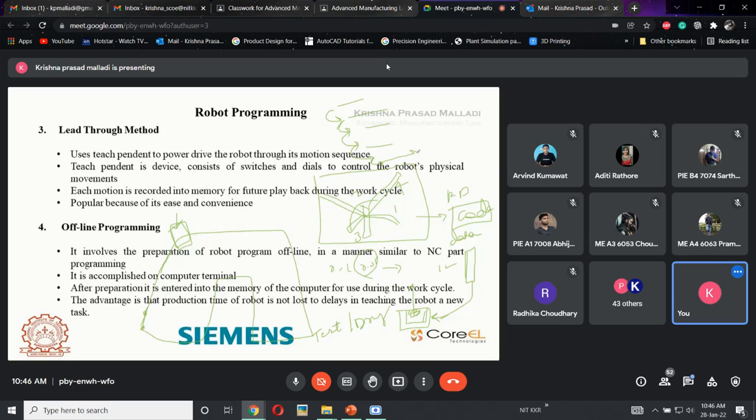If the cylinder height is some 10 centimeters from the ground and the robot is moving at 9 centimeters, then in this application I'm going to change z from 9 to 15. I will modify it, so the robot will move from the upward direction, and the next moves will be synchronized automatically. Now I will try it.